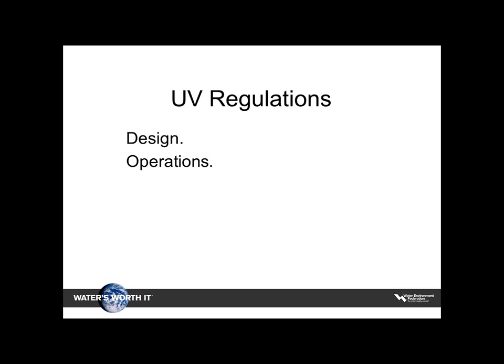Now, what's really interesting is that from a wastewater treatment plant standpoint, if you're operating a membrane bioreactor, that's easy. Probably your E. coli is not going to get through your membranes. So there was a debate that's gone back and forth on, well, if I meet my permit, do I have to disinfect? At least we're dealing with a requirement to run your disinfection system all the time, regardless of really whether you're making the E. coli number, because like I said, out of a membrane bioreactor, you will probably be making the E. coli number.